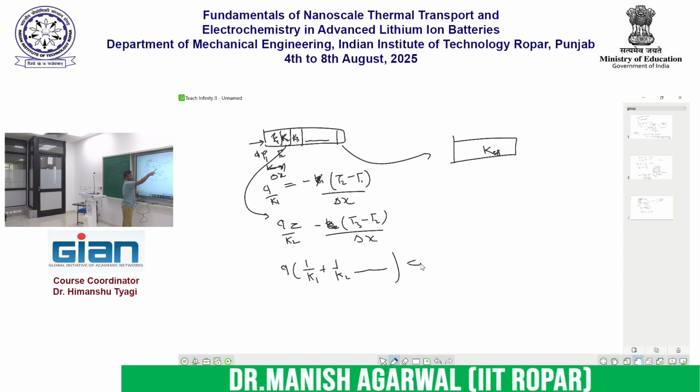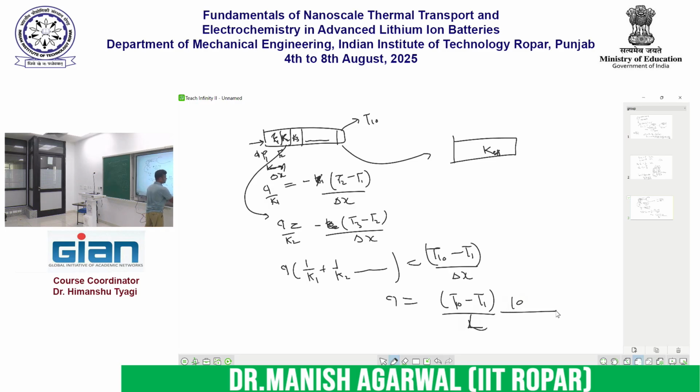There will be a lot of cancellation, T2 will cancel like this. So let's say the final one is T10, so then it will become T10 minus T1 divided by delta x. So the Q is going to be T10 minus T1 over length. The length, I assume, is the 10 blocks, so it is going to be delta x into 10, right? So length L and 10 here, and that is going to be 1 upon K1, 1 upon K10.